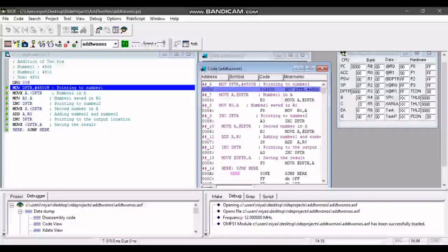How many bytes is this one? Like in the number system when we studied, 00 corresponds to a byte, 45 corresponds to another byte, 90 corresponds to another byte. So we have 3 bytes for this single instruction. That is the machine language. Where will those 3 bytes be saved? I had told you each memory location will save 1 byte. So at 0000, one byte will be saved, at 0001 the next byte will be saved, and at 0002 the last byte will be saved.